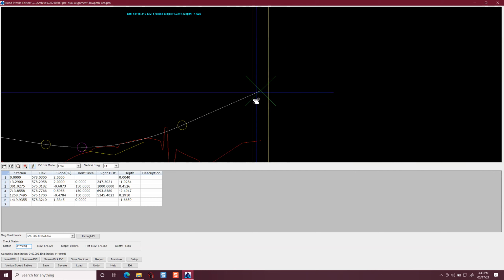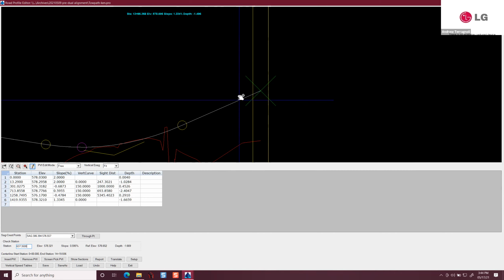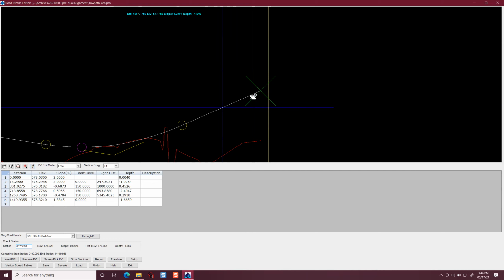if you're not holding the main road crown, then when you first set your ending elevation, which it already knows because of the profile elevation, when you process, it recomputes the surface. It takes this side road that hits the center line for the main road and changes it right in here. It puts in these little fudgy 15-foot PVIs to get you up and over across that center line, and it does the same thing to the main road.